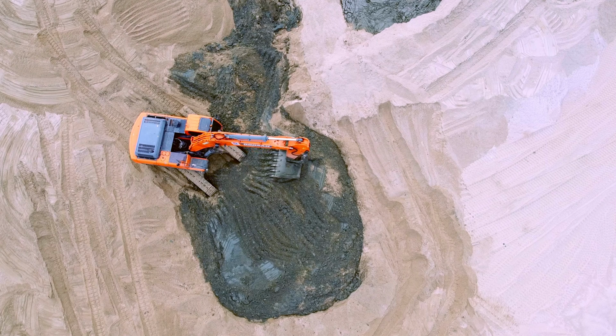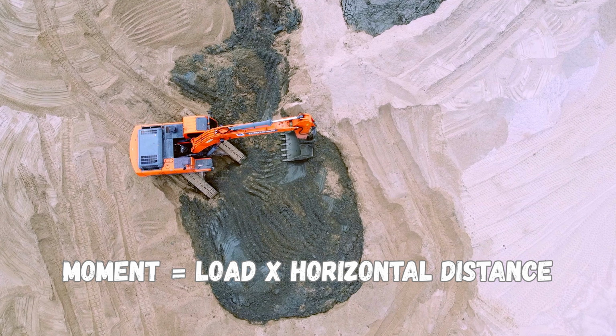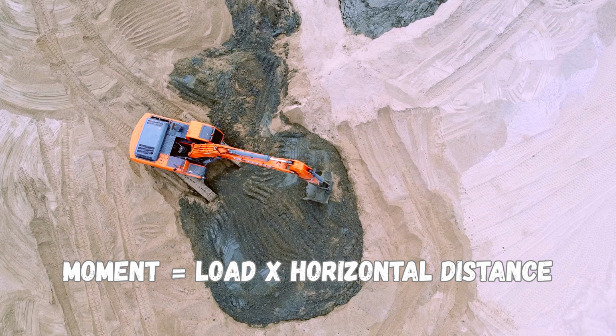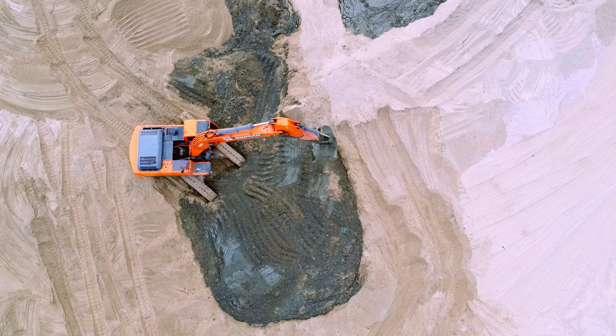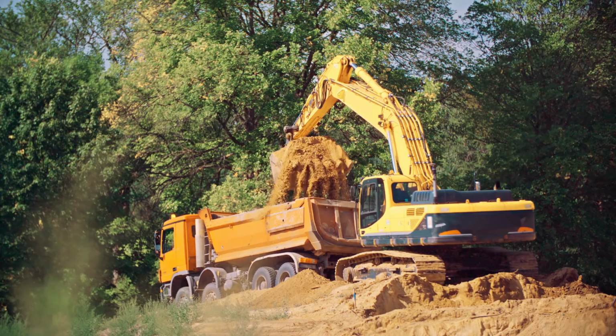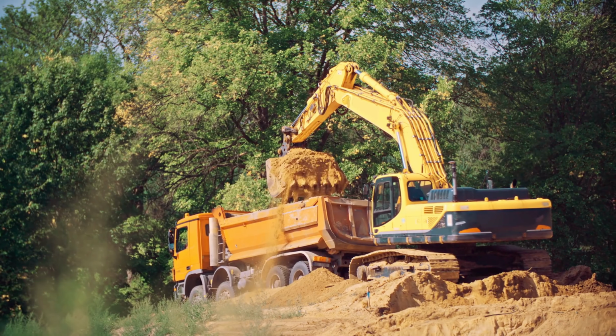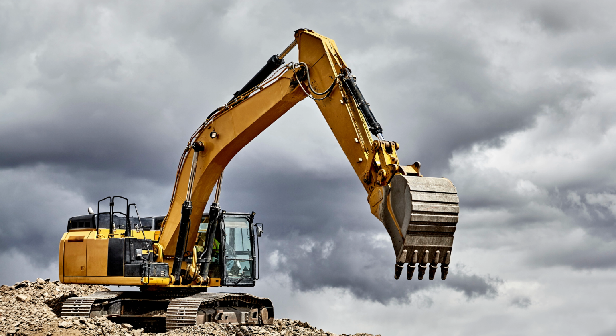From a mechanical perspective, the tipping moment can be expressed as the product of the load and its horizontal distance from the pivot point. If this overturning moment becomes larger than the resisting moment generated by the weight of the excavator itself, the machine may begin to lift one side of the tracks or even tip over. The resisting moment is mainly produced by the machine's own mass, the counterweight, and the position of the center of gravity relative to the tipping axis.